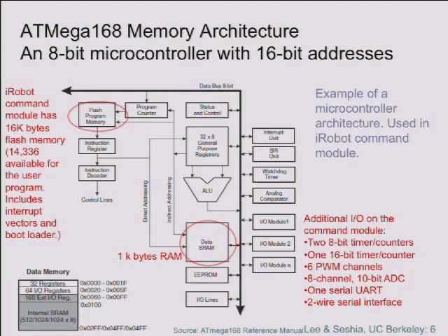Yeah, so what is 2 to the power 16? How many locations the address? No, I mean, what number is it? It's about 64 kilobytes, right? And but there's only 16 kilobytes. Actually, no, sorry, this is the data memory. There's only 1 kilobyte. What's the discrepancy there? I mean, the 16-bit addresses, but I've only got 1 kilobyte of memory.